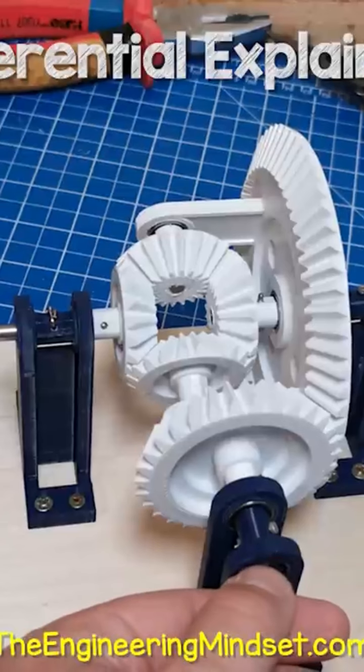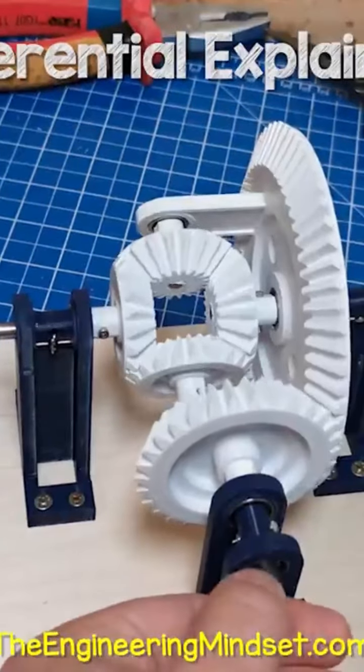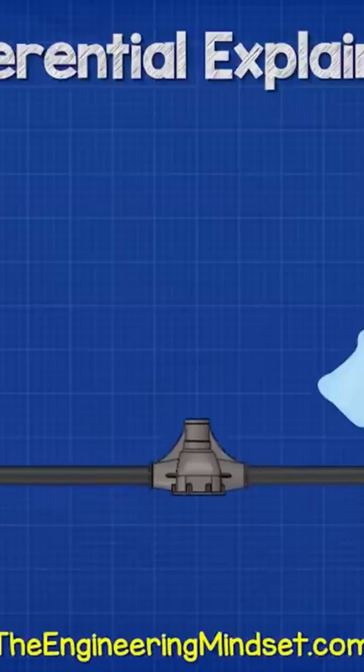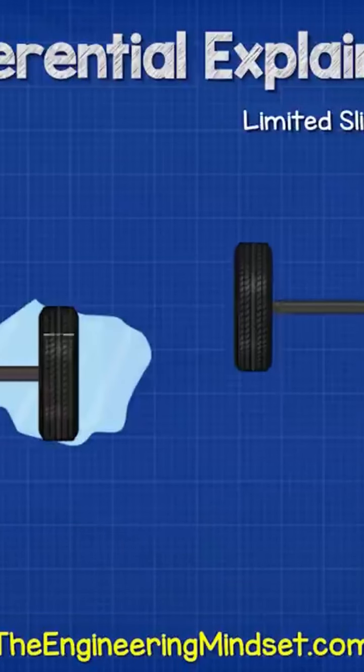We can see from this basic model differential that if I hold one of the wheels, the other can still rotate. This is known as an open differential. The problem we face is that if one of the wheels travels over a slippery surface, such as ice, almost all of the engine's power will transfer to the wheel with least resistance, and so the car becomes stuck. To solve that, we use a limited slip differential, and we will see how that works later on in this